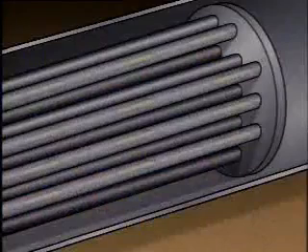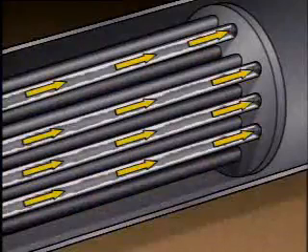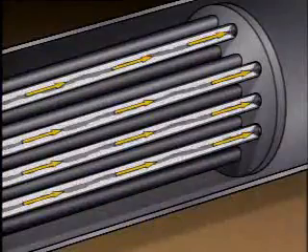One common cause is impurities in the fluids passing through the heat exchanger. For example, in a process that uses water, impurities such as calcium can come out of the water and form an additional layer of material.